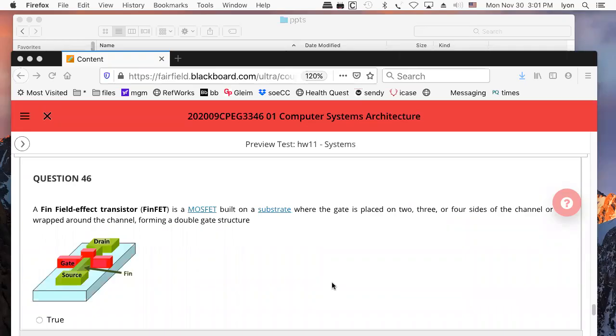So Intel comes along with this idea that instead of competing based on actual transistor size, they're going to build up in 3D. And they do this by creating a new kind of transistor called the FinFET. A field effect transistor is a voltage variable resistor instead of the bipolar junction transistor, or BJT, which is known as a current controlled current source.